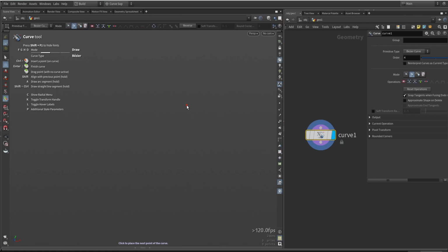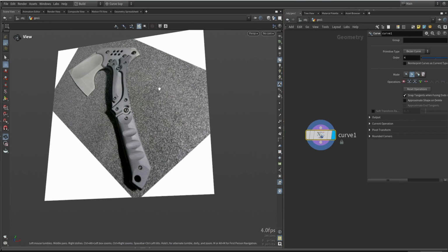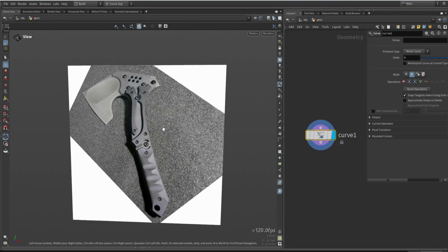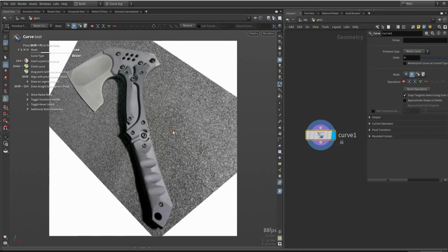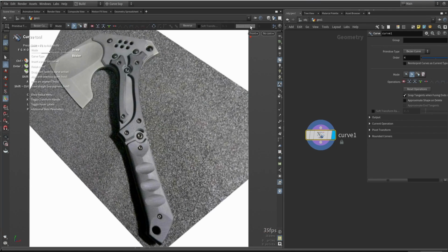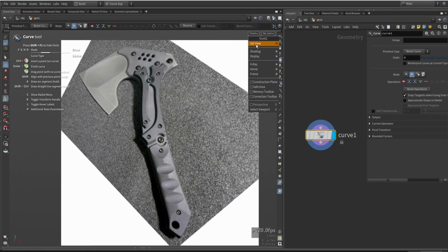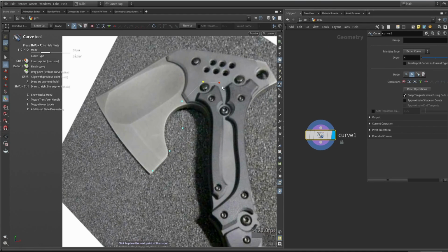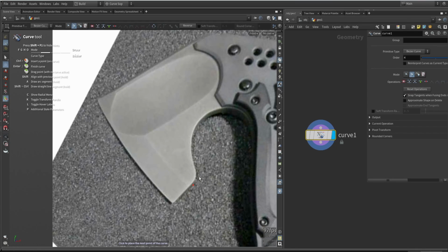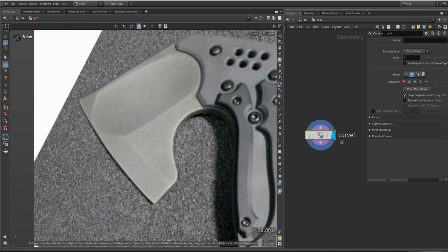Now, how to preview our mesh. In case you did not see a reference, we're going to go here to the side and say show all objects. So we'll show all the objects that you loaded in Houdini. Then we're going to press spacebar 3 to go into the side view or the front view. You can also click it here and go to front view. And now we will start to trace with the line. So let's reset it again. Essentially what we want to do is a simple trace, and we can always modify it slightly afterwards.